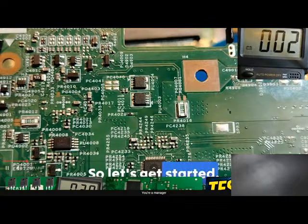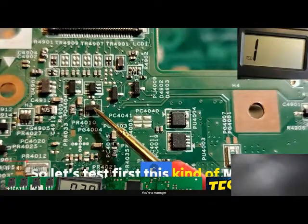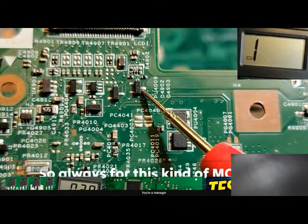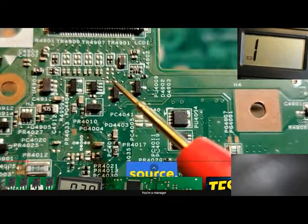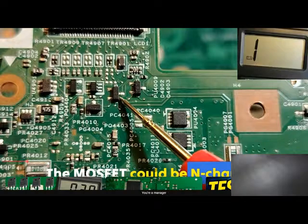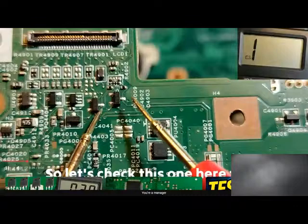So first, make sure you select the diode mode on the multimeter. So let's test first this kind of MOSFET. As you can see, a 3-terminal MOSFET. Always for this kind of MOSFET, we have here the gate, drain, and source. The MOSFET could be an N-channel MOSFET or a P-channel MOSFET. I'll show you everything. So let's check this one here first.